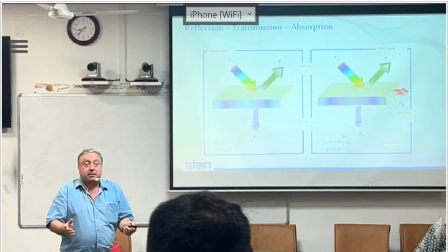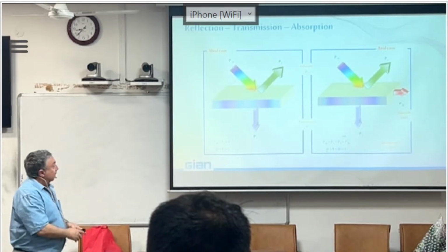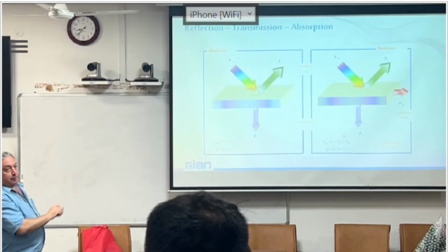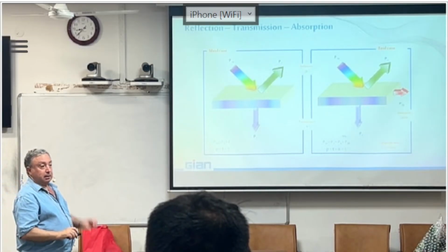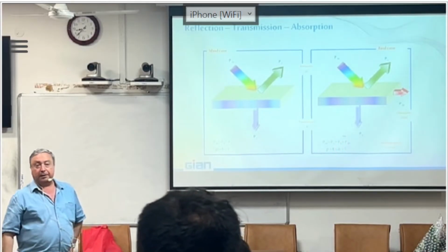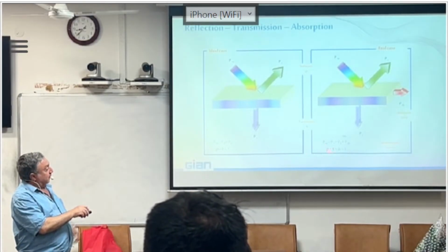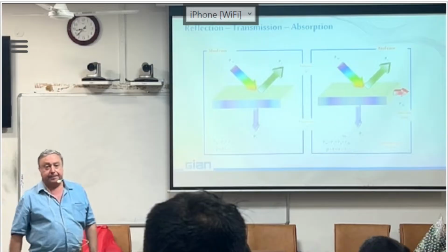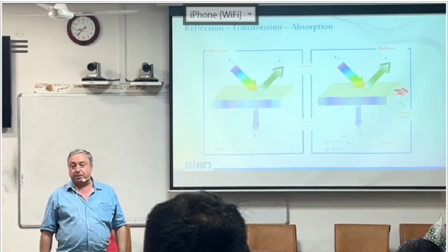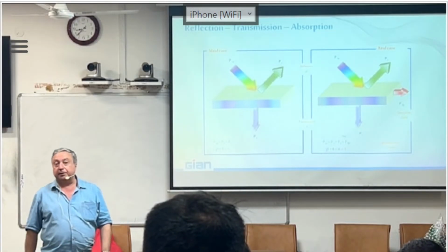It cannot do anything else, otherwise you split the photon in two. In a real case, some of the radiation can be absorbed inside the bulk of the material, and then you have to add a third coefficient, the absorbance α, and the sum ρ plus τ plus α equals 1. Here my photon has an α percent chance to never get out of the material, but to generate heat.